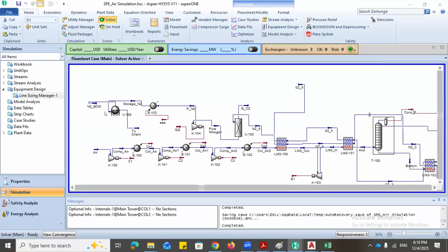When we are designing a storage tank, there's what we call low, the medium, and also the high. There is a particular maximum height that the liquid in that tank should reach. It should not get up to 100%. Why should it not get to 100%? We must keep a space for vapor to be there.